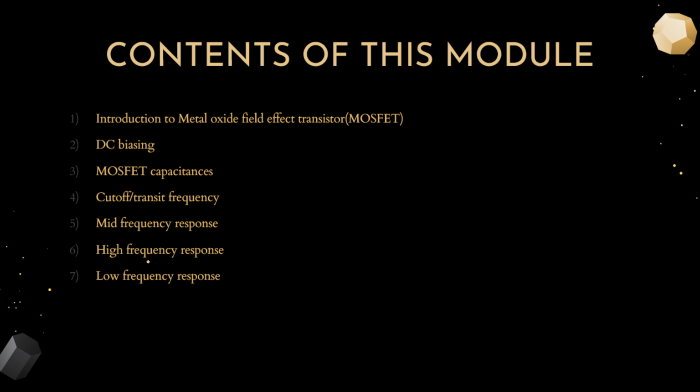The internal capacitances affect your low frequency, and the external capacitances, which are the bypass and coupling capacitances, they affect your high frequency response. All of this is, I mean, I just said it the other way. The internal capacitances affect the high frequency, and the other ones affect the low frequency.